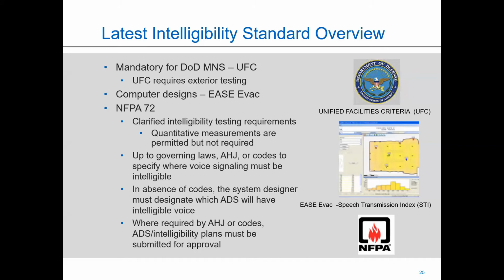And this is really where I go with intelligibility when I'm talking about it, just straight up. It's a design. You put in your design, you put in your measurements, your prints, and then you could lay out speakers based upon the criteria you're looking for, whatever's in the spec. I need this above ambient. This is what I need in dB, and this thing lays it all out for you. And our guys are actually really helpful when putting these together. These services are utilized all the time with our customers.